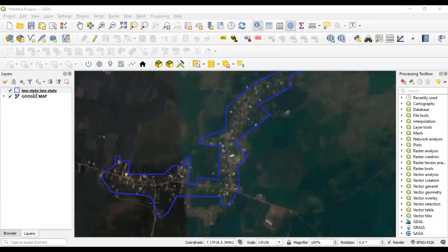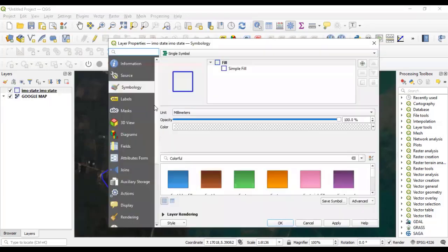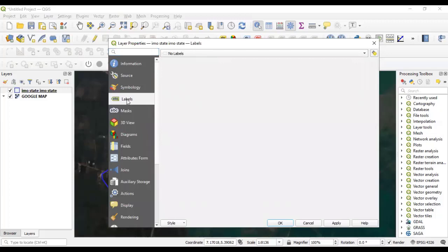And then another thing I want to show before we stop, because I'm trying to make sure that we finish by 4. So if you click on this, the same information, guys, double click on it, where we change the symbologies, make it transparent. If you look at the next tool here, it is label. What I mean by label is, let's say in AutoCAD, annotation, like labeling. When you do drawing in school, they say label it, draw with label, right? So when you say label, it means to add information, to display information about that object.